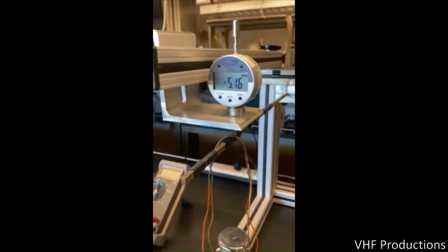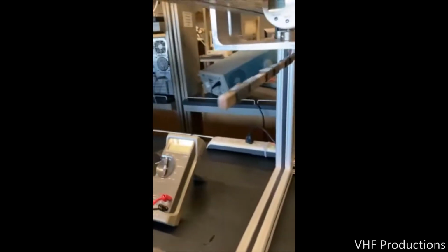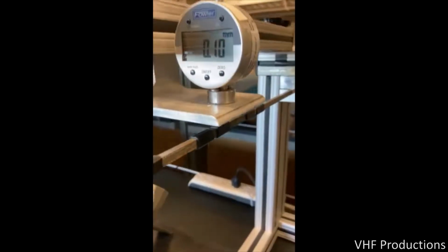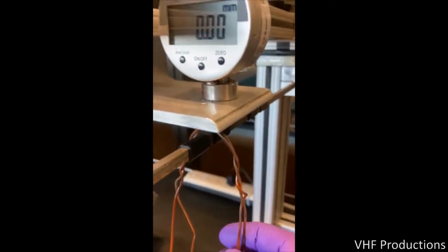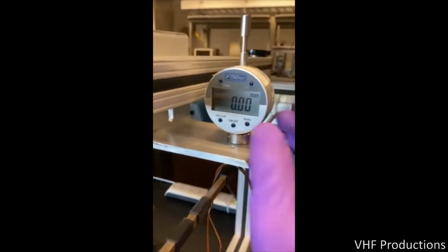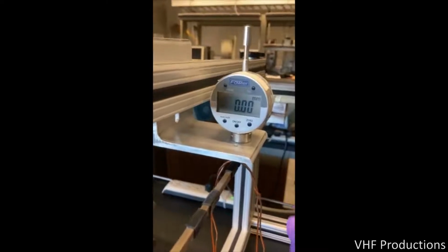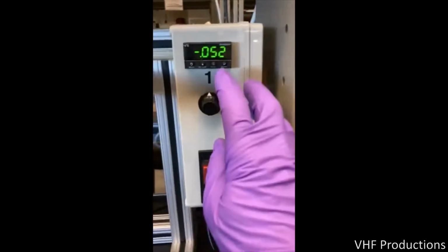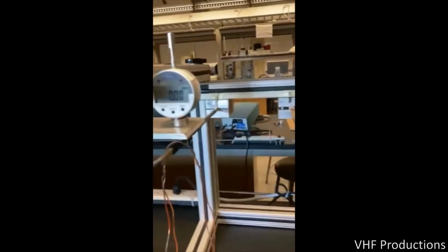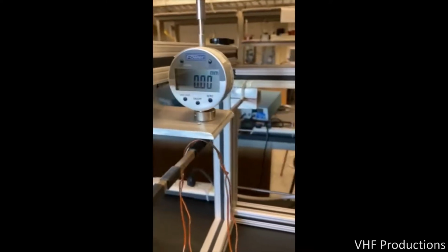It's worth noting that for the actual experiments, we are not using the Wheatstone plug-and-play platform. That was a demonstration module. In the actual experiment, a Wheatstone bridge is built into the white box on the right side of the loading frame, where the black knob selects between beams 1, 2, 3, and 4, and the display is set up to read the output of the Wheatstone bridge between pins B and D. But the entire Wheatstone bridge and its power supply are all contained inside the white box mounted on the right side of the load frame.